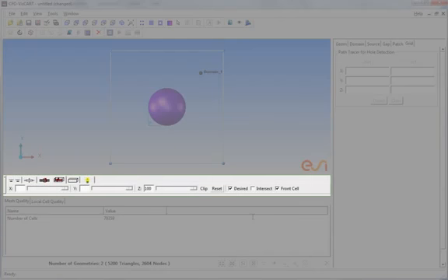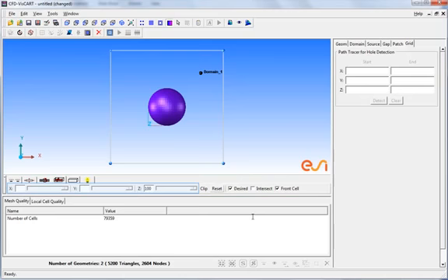The entity bar provides options for geometry and grid blanking, visually scaling and rotating the model, cut planes, among others. Cut planes can be used here to view the generated mesh, by sliding them through the model. We can also specify a location of the cut plane by typing in the value. Let us place the z-cut plane at z equals 25.